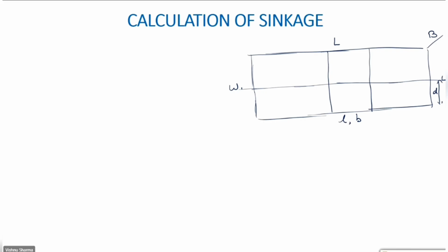Okay. Now this midship compartment gets bilged. And this causes the vessel to sink to a new water line W1L1, and this new draft we will always call D1, and it is this thing which is called sinkage, beta. Have you understood, beta? Yes, sir.